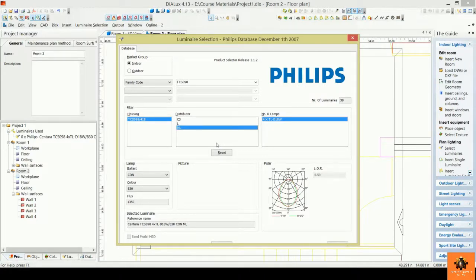This is because there are some losses of the luminaire's lumens output, so we get this light output ratio to represent the ratio between the actual lumens falling on the surface and the total lumens that the luminaire should give us in the ideal case.